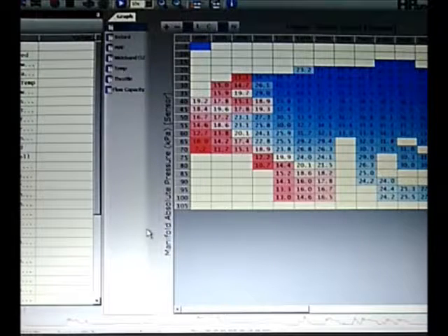Most of the time, I don't know anybody who's got more than one channel in use at any given time, and it's usually because they have a wideband, so this probably won't be an issue for you at all. Just hook up your signal wire to any of the numbers and just pick the corresponding number in the software until you get a recording here.